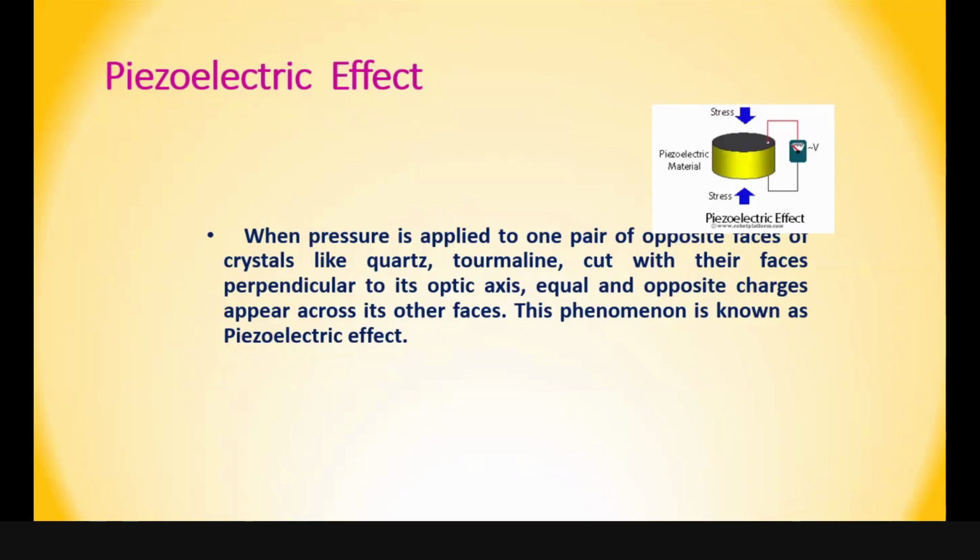Let me start with some examples. You might have heard about shoes with which you can charge mobile phones while walking. You cannot charge while standing; you need to walk. So in those shoes, at the foot, you will have a small chip of piezoelectric material, a chip of quartz or a piezoelectric crystal. Now you are walking, so when you walk, you are applying force on the crystal, and due to that applied force, electricity will be generated. That means mechanical energy is converted into electrical energy.